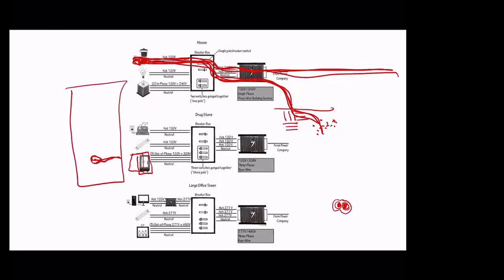Every time they move it, they yank on the wire, and it rubs and rubs and rubs against the grommet. Eventually, the hot wire is actually touching the metal back panel of the freezer. Let's say one of the wires is touching. 120 volts is electrifying that back panel. So the whole thing is like a bare exposed wire. But because the wheels are rubber, it's not grounded, so the electrical breaker box does not know to flip off, because it's not getting hot.